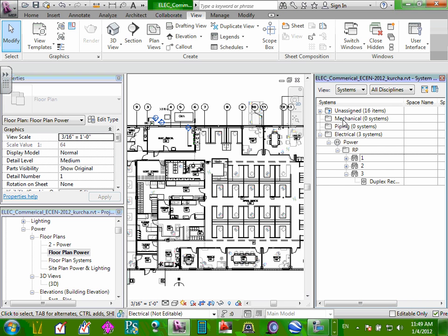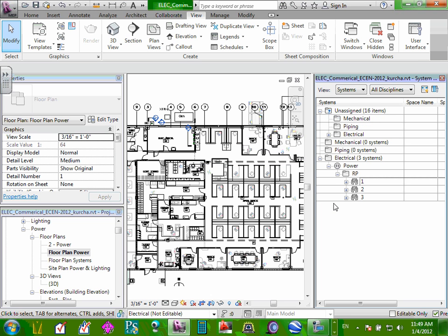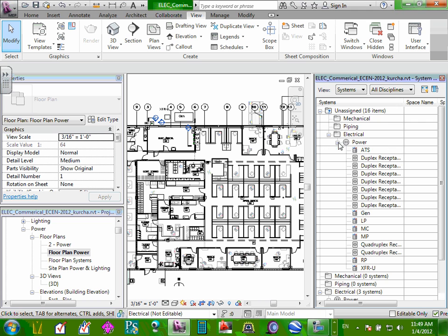The other thing it shows you is the receptacle assigned to each circuit. Can you guys see it? If you go to Unassigned, it will tell you all the electrical equipment in your system that has not been circuited yet. So there are 2 very important things, guys. Under Electrical, Unassigned, it shows 16 items here, receptacles that have not been circuited yet, and we drop them.